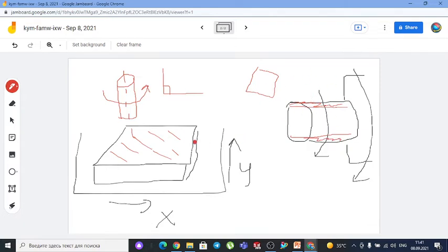So the main difference between milling and turning is that in milling the workpiece is prismatic and fixed on the table. In the turning operation, the workpiece is cylindrical and it rotates with the help of the spindle. The tool can move in this direction, the x direction, and in this direction, the z direction.